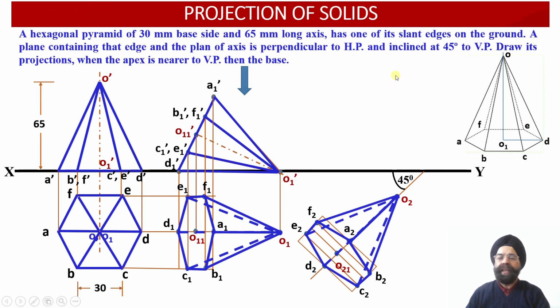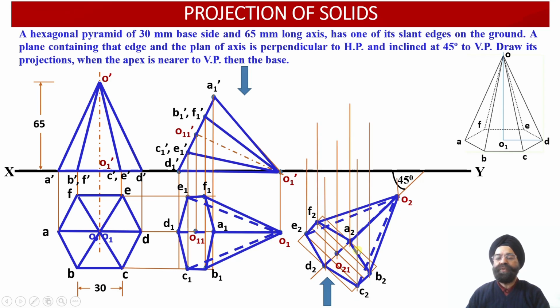Now let us obtain the front view elevation projections for this oblique hexagonal pyramid. Now how will this be possible? When the observer is going to look at this hexagonal pyramid from this orientation, then how many points do we have in the front view projection? A total of 8 points are available in the plan projection view. So from each one of these 8 points, we need to draw the vertical projector lines and extend them into